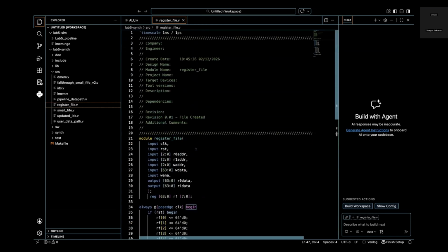And then it is mentioned that we need to use the core IP. So in Xilinx ISE 10.1 under sources, when we add new source, we went ahead and chose the IP core generator. Based on their specifications, we have to generate a block RAM based dual port synchronous memory with 64-bit wide data and 256 entries. So basically that's 8 bits address. That will be our DMEM, data memory.